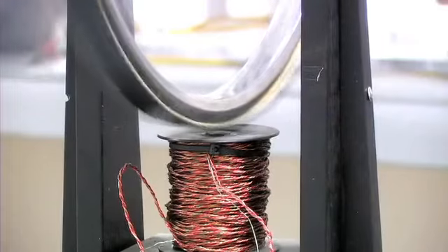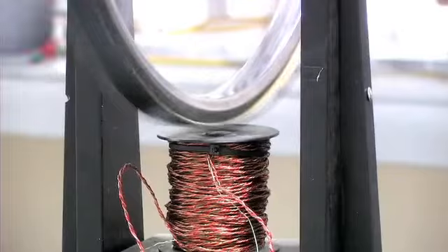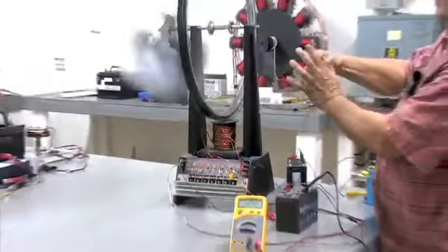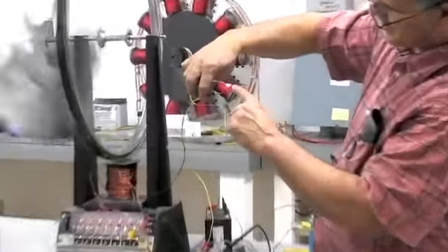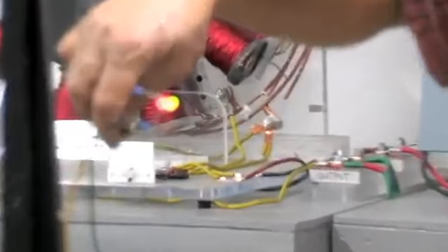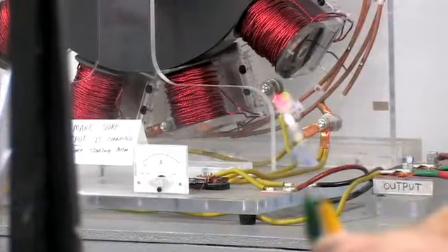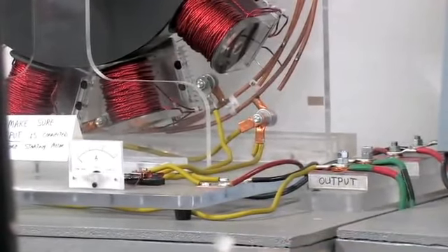See, so you can make a simple set of timing lights by using two LEDs back to back and a couple of resistors so that you can see the firing across the coil, and you can see it here. You can see one is the charge and one is the discharge. So that's one way you can do it, to find the exact timing.